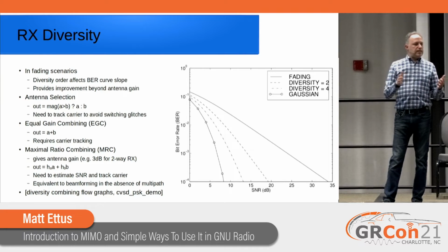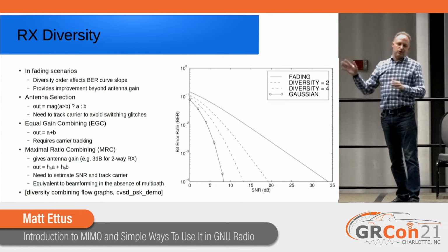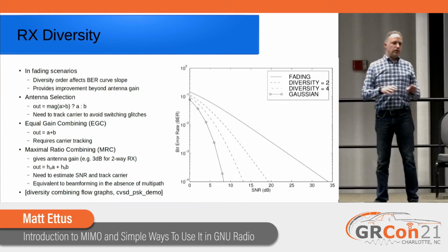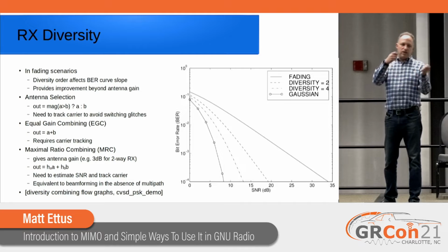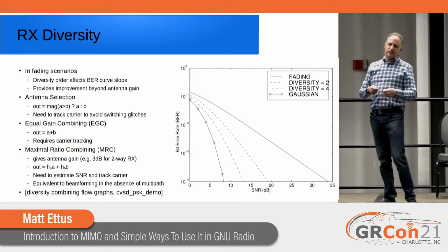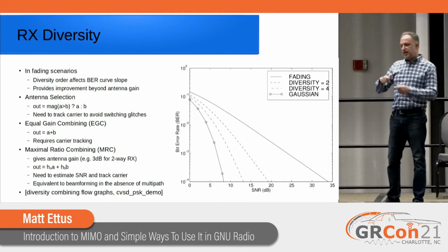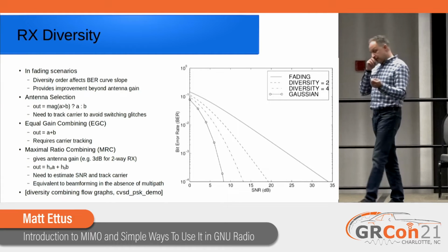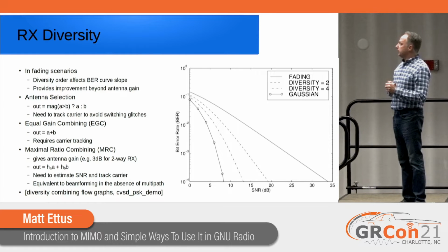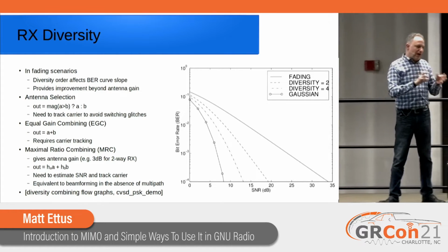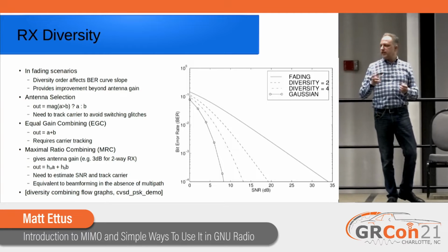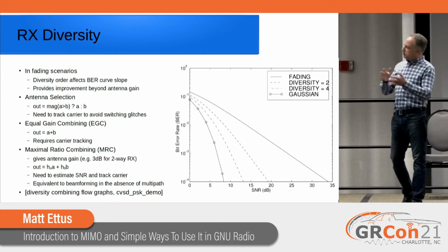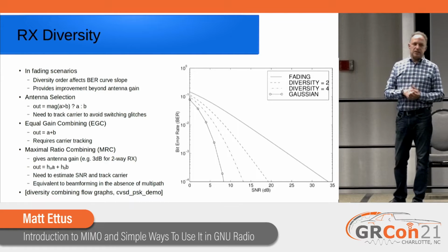But it's really easy. And typically if you're doing this, you're usually doing it entirely analog. You're not doing it in code like this, because if you've gone to the effort of getting 2 signals into the radio, you wouldn't bother using this method. But if you have, say, 2 power detectors, you can rapidly switch between the 2 signals, and that's what their car radio was doing. And you kind of have to track the carrier, because when you switch between the 2, it'll glitch, and if it's FM, you'd hear a little click, but in general, it's a very easy system.